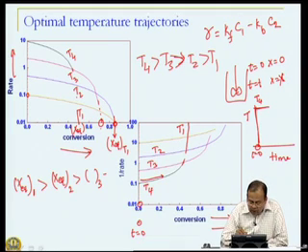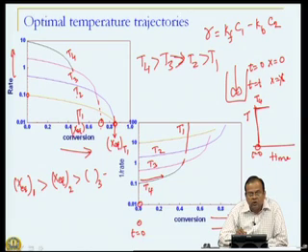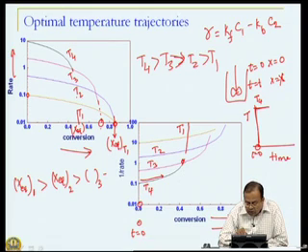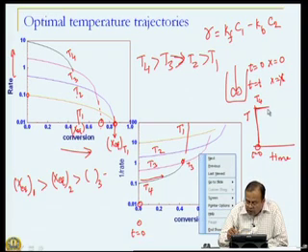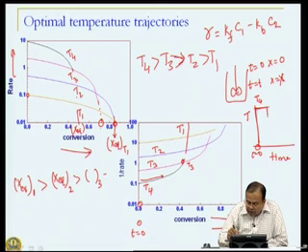That means I have lost on equilibrium conversion if I keep temperature T4 for a long time. So, suppose it crosses over here, what should I now do? I see now that temperature T3 is what is giving me the lowest 1 over rate, or in other words, I should decrease my temperature to T3.